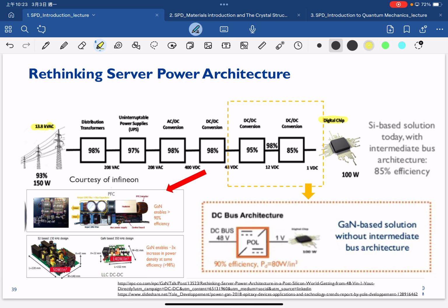So now we all know for low power operation, what we explained before is we try to have as low a power as our digital chip can operate, which can be 1 volt. As we already mentioned previously with the ID-VG curve, we can try to make transistors that have 1 volt operation, but with a very good on current here. So usually when it comes to our digital chip, we try to have as low a voltage as we can. In this case, which is 1 volt.